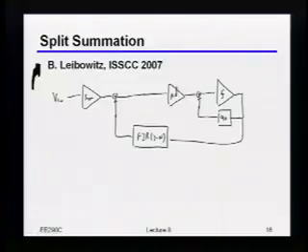So absolutely, it depends on how big the ISI is, but the only issue with doing something like this is that, unfortunately, you're going to go through some nonlinearity getting from here to here, and you will still have that ISI left. If that nonlinearity is big enough, then that could indeed cause this to not actually work. In most link channels and most of the swings that I deal with, that's not too bad of a problem. But you're absolutely right.